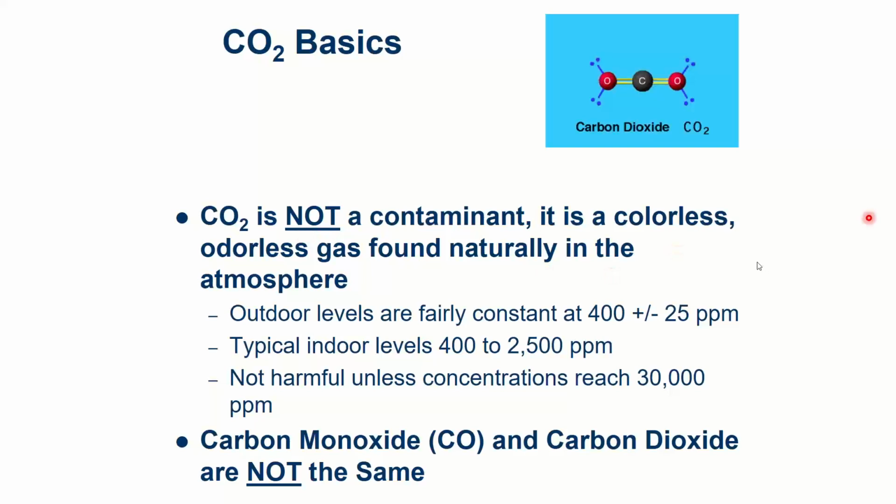So normal levels in an indoor space, they're showing you here down to 400. That would be like if you're in full economizer mode and you're bringing 100% outside air in. Then maybe you're down at that level. But normally you're going to be like 800, 1,000, 1,100, 1,200, 900, something like that. If you're up in this category, 2,000, 2,500, you're doing a really crappy job of ventilating. We should be nearish 1,000. We'll talk about set points in a minute. We should be near 1,000. That's kind of a place to remember.